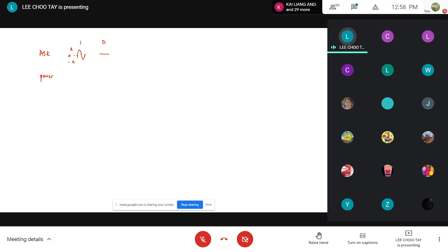What is the power when a 1 is being sent? A squared over 2, right? Sinusoidal wave. The power is what? The V peak over root 2, right? V peak over root 2, that is your RMS value. Then you square it, you get your power. All right, so there is A squared over 2.